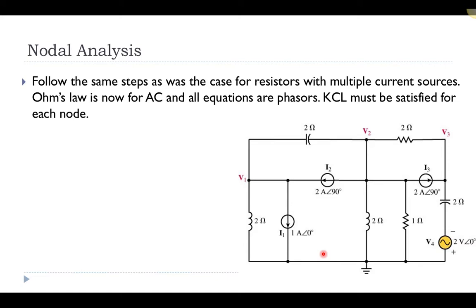Basically we can apply those same steps, and we have to use Ohm's law for AC, where everything is in terms of phasors. And we will apply Kirchhoff's current law at each of the nodes. So let's talk about the steps that we would follow.